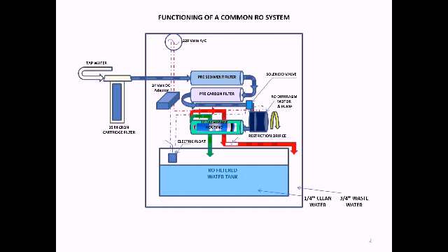Now the RO filtered water goes into the tank fitted into the household RO system only, and in between the RO membrane housing and the filtered tank we can also put, as per our convenience, and some of the suppliers do it also, a mineral cartridge or an after carbon filter cartridge, so that the final RO filtered water is not only TDS controlled, it has got its desired minerals back also.